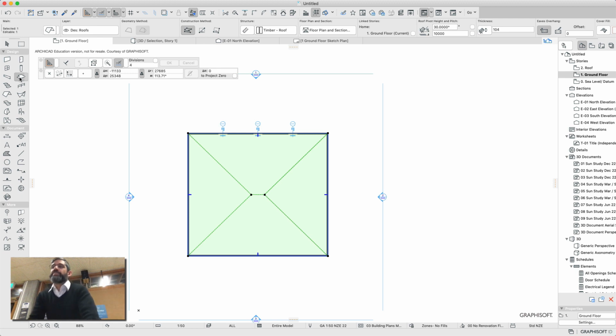Now our slab in this case is a little bit complicated because we're not using a slab in the same way. We're not defining the ground level and going down. We have to go above the building and go down through it. Okay, so our building's 10 meters. So I'm going to throw 12 meters in there. I think that should probably work.